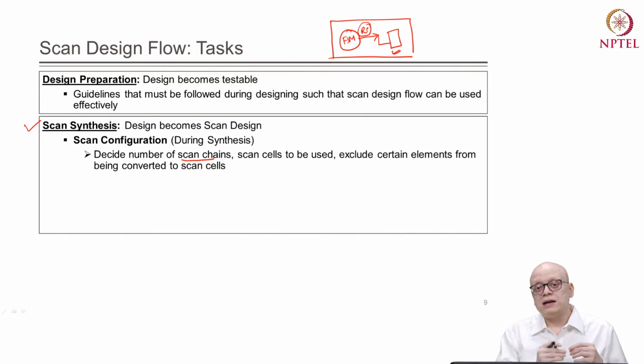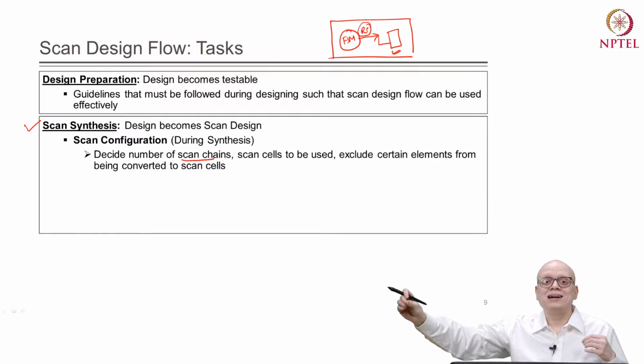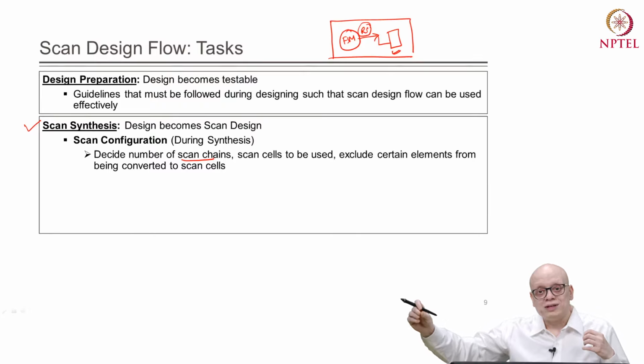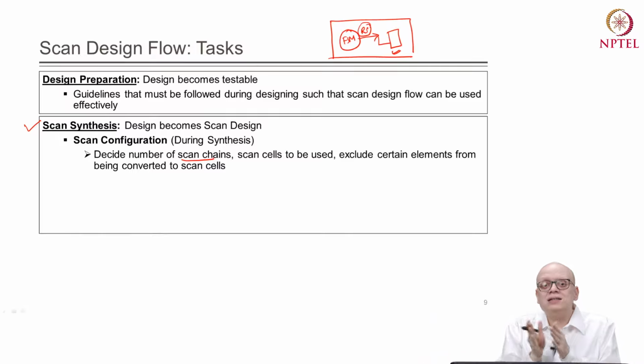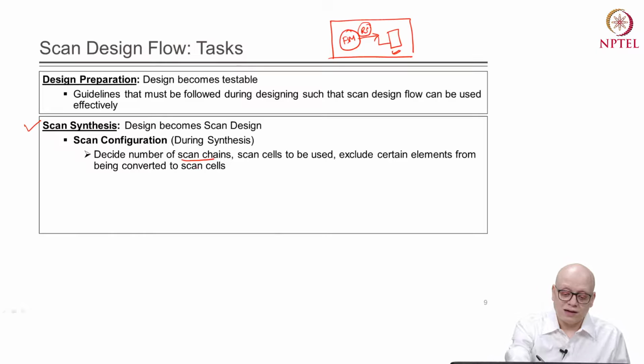If we keep one very long scan chain in our design, then it may take a long time to test and load the pattern. And therefore, we can partition this into smaller scan chains. And how many such scan chains we want in our design, we can give as a configuration parameter to the tool that is implementing the scan synthesis.